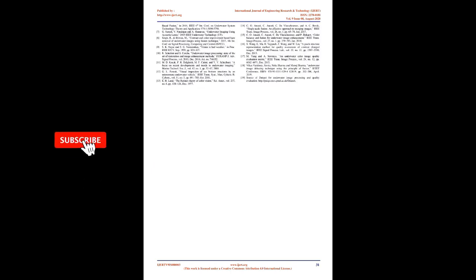Now the upsampled version of the low-pass image is subtracted from the input image. It approximates the Laplacian, and the decimated low-pass image is used as the input for the successive level of the pyramid. The m-th level Lm of the pyramid can be calculated by the following equation. Here, Gm denotes a sequence of m low-pass filtering and decimation, followed by m upsampling operations. In the above equation Lm and Gm represent the m-th level of the Laplacian and Gaussian pyramid respectively.